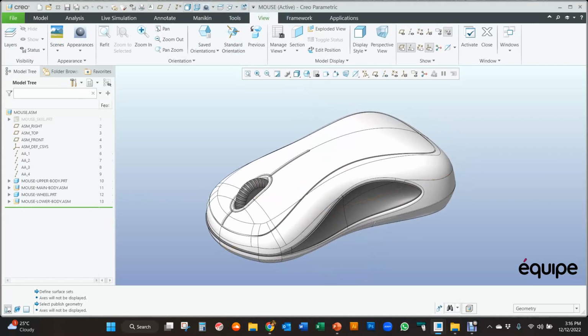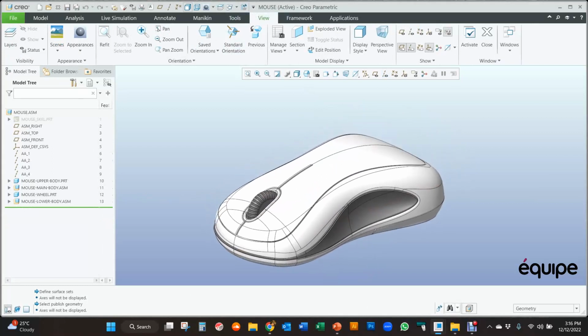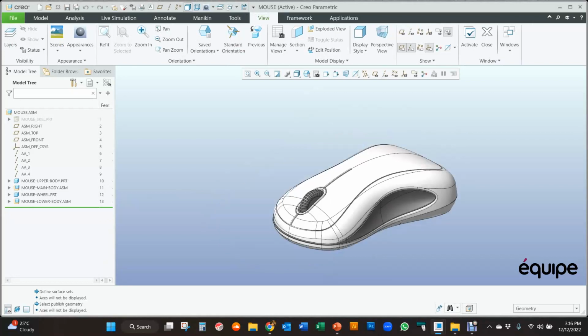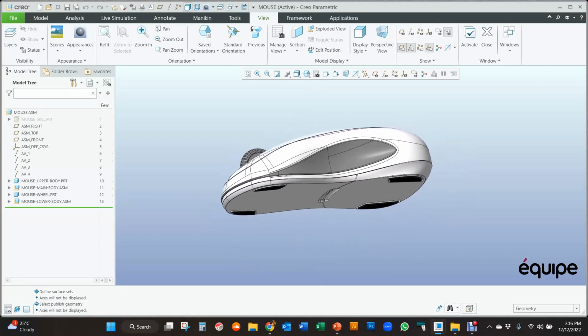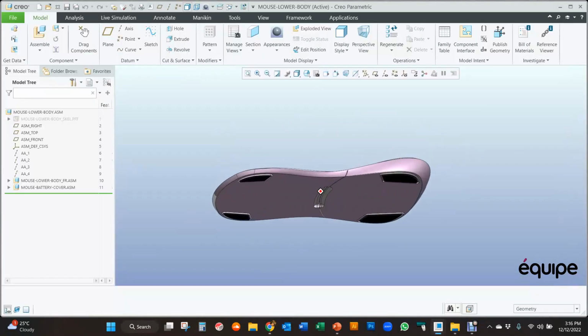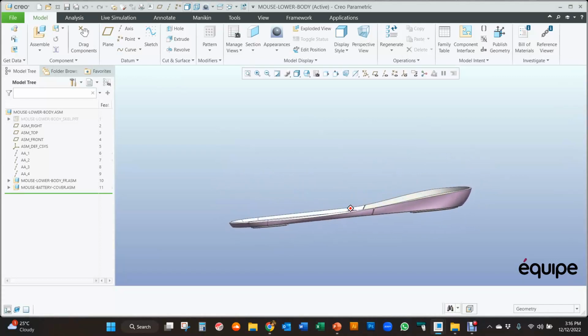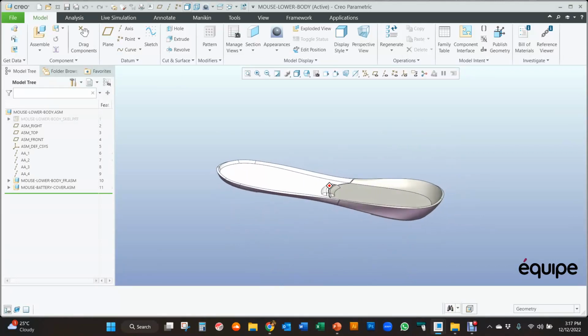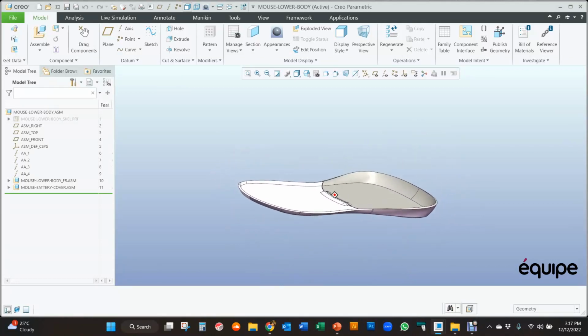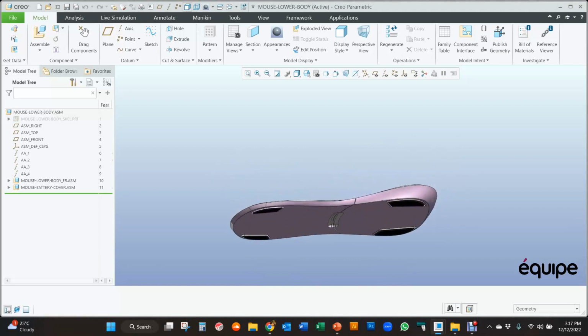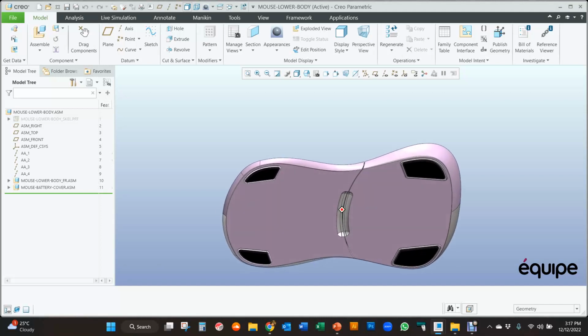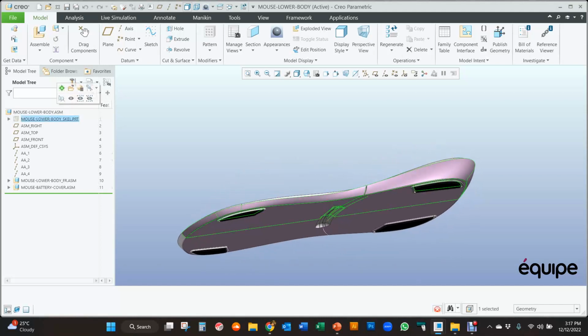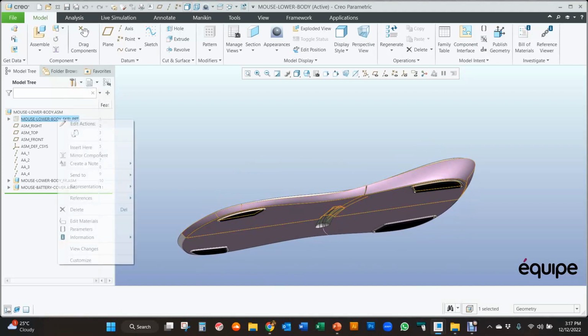So this was an example for the wheel of external geometry sharing into a part. Another way of doing it, say, is having a sub-assembly skeleton. So we're not trying to keep references higher up the model tree. We're really trying to push them down as far down the model tree as we can, just to make for really light but robust modeling. So this one, I've got a skeleton which controls the lower body sub-assembly.